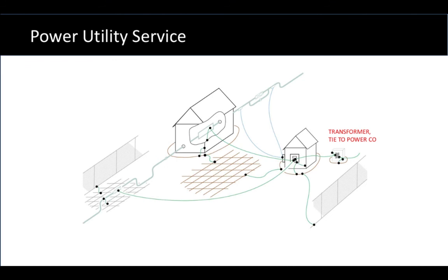Let's say that this station actually was a compressor station or a large pump facility. It could be that there's much more equipment and piping than I've shown right here, and there are many points of possible contact of the pipeline to the grounding system where the CP could be shorted out. Those sites can be so complex that you can't even sort out all of those bonds, because if you missed even one, it's like you had done nothing at all. Then you might be able to see how separation from the power company becomes important. Because by default, power company grounding systems connect to user grounding systems for safety. And it's that tie that we have to address.